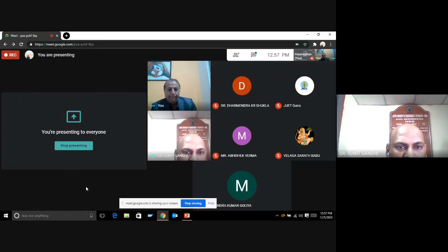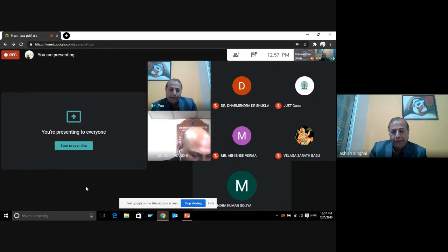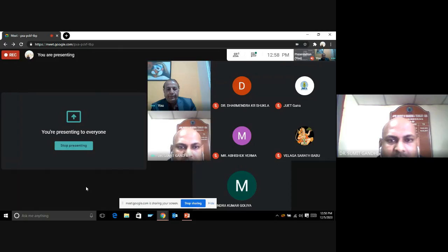Okay. So then another question is from Mr. Milind Gupta. He is asking, can a partition wall be constructed of AAC, autoclaved aerated concrete block? Yes, AAC blocks are primarily meant for making walls only. They can be made for internal as well as external walls. I mentioned this in my presentation also. Internal as well as external, both walls can be constructed by AAC blocks. Yes, I think the participant may definitely be satisfied with this reply, right?